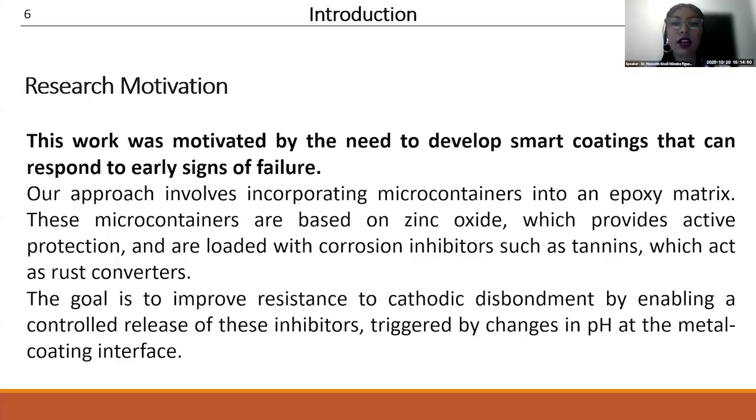These microcontainers are based on zinc oxide, which provides active protection, and also they are loaded with corrosion inhibitors such as tannins, which act as rust converters. And our goal is to improve the resistance to cathodic disbondment by enabling a controlled release of these inhibitors triggered by changes in pH and the metal coating interface.